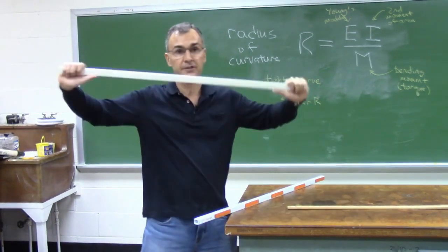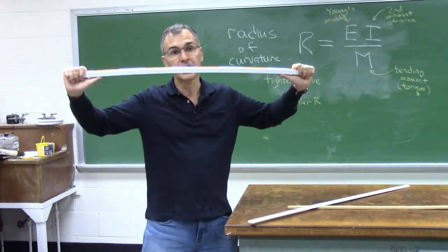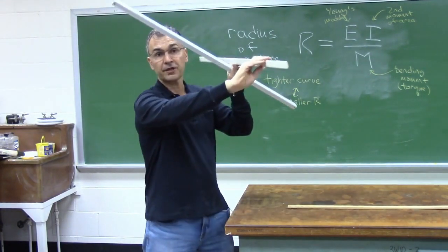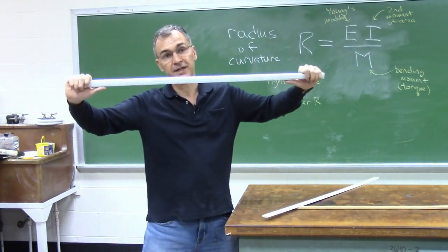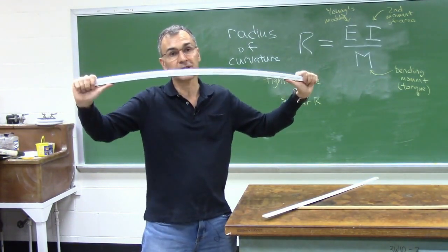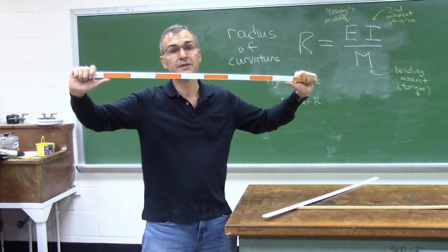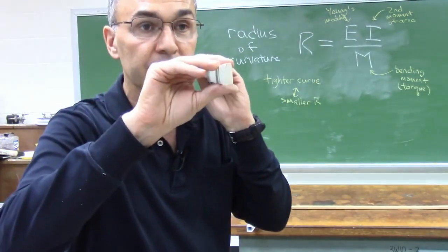I guess if I compare it to this, it seems as if this box beam shape is less stiff than the plastic when it's on end, but it's more stiff than the plastic when it's on the flat. So this is also plastic. Yes, it seems as if this box beam configuration must have a second moment of area, which is bigger than this, but smaller than this.